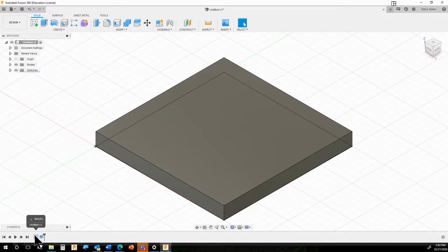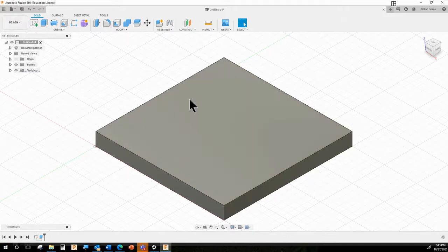And if you don't, just X out of this file and create a new file, which you can do with the little plus sign, or under here, create a new file. Just draw a 100 millimeter square like I explained earlier and extrude it 10 millimeters, and just do those two things, because you might have messed up in between. And if you did, it's going to mess up what you're doing next. So please make sure you're right with me where you're supposed to be, because if you're not in the same workflow, it will act unpredictably.